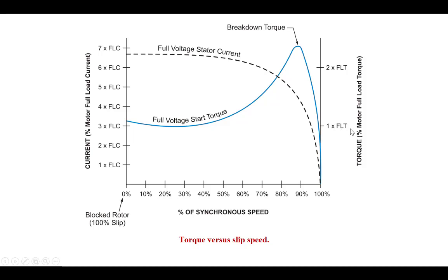And the thing to keep in mind, of course, is most motors are designed to provide more torque than you use at full load, so that if we accidentally overload the motor a bit, it will continue to work for us. And if we get past the full load for this motor and put more load on than it's rated for, it will just continue to slow down and produce more torque. Now it's also drawing more than the rated current that it would draw at full load. And so eventually, if we leave it overloaded, the extra current it's drawing should cause the overloads to trip.